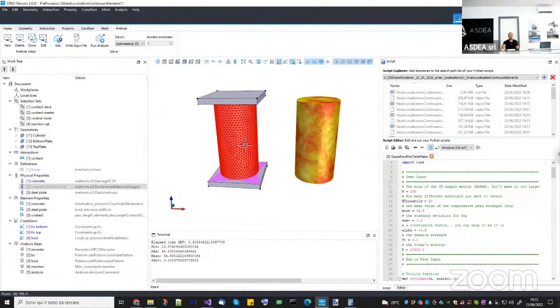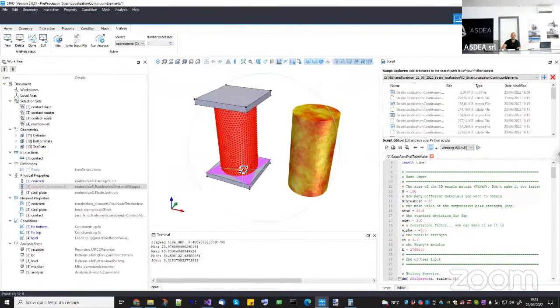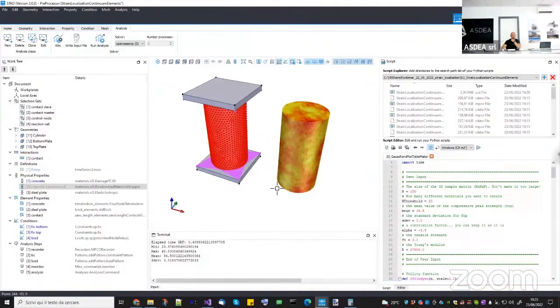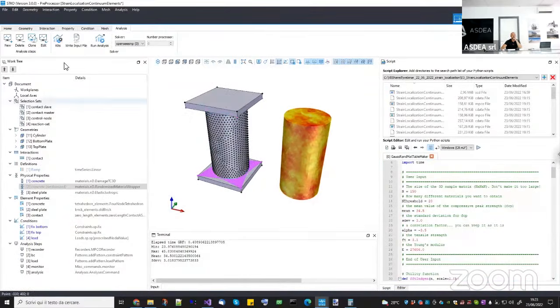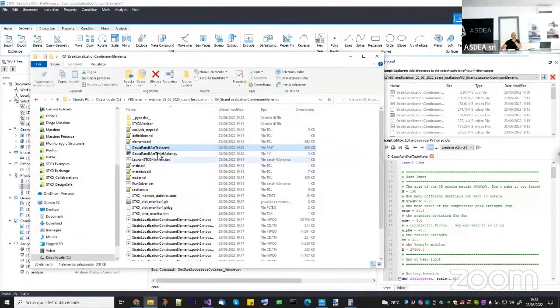It generates a file according to these properties that you gave, and the mesh that you created. So every time you create the mesh, you can run this file, and it will create the random material table for you, okay? So ultimately, you will be able to have a material model, but of course, when you change it, the drawing will go away, but it's not important, it was just a preview. But now it generated this random material table.